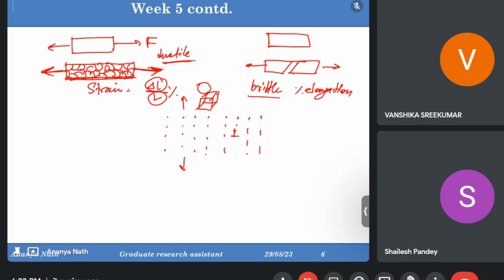Okay. So I was telling you about the dislocations. Till that point we have understood how we are accommodating the strain, what it means by this sentence of accommodating the strain. And our job is to harden the material, which means our job is to restrict the dislocation movement. If the dislocation movement is resulting in the percentage elongation, showing the ductility in the material, our job is to harden the material, meaning decrease the ductility. So the ductility is the result of the dislocation movement. This is why we are trying to restrict the dislocation movement anyhow. So we go for the alloying.